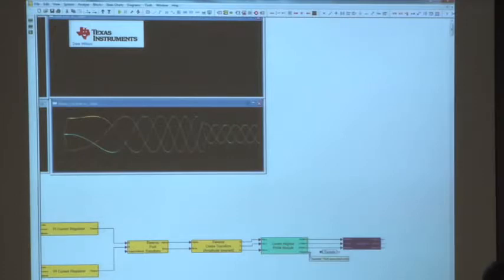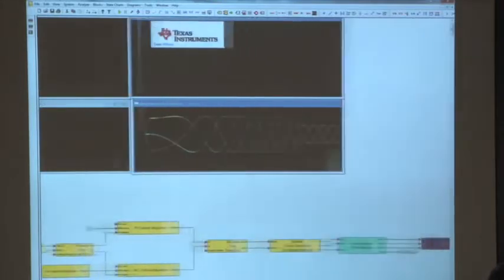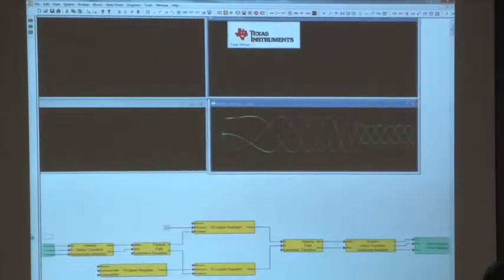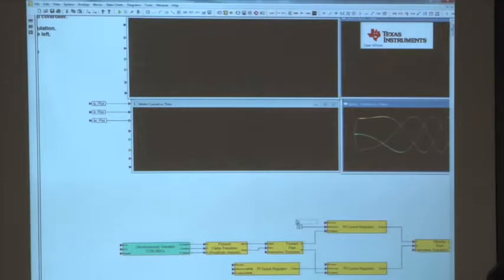Now when I drag the output pin sample on the center aligned PWM module over to the input of that variable, I have now created a variable which has that signal name on it. I can now go back to all these things that had the execute pin on them. What I want to do is click near the sample variable, click and drag so that I select it. With it selected, it's going to turn black. I now go Control-C, Control-V, and that creates another instantiation of that, which I can now put anywhere I want.